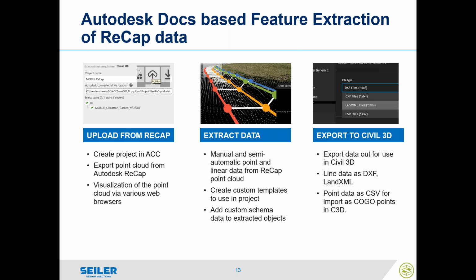and assistance. So in about mid 2024, Autodesk started introducing the ability to load your Recap files into the Construction Cloud and visualize them there. And then they've moved these extraction data tools into that software. And we can upload directly from Recap. We create a project in the Autodesk Construction Cloud. We export our Point Cloud up into the Autodesk Construction Cloud, and then we can visualize on any web browser and do our extraction there.